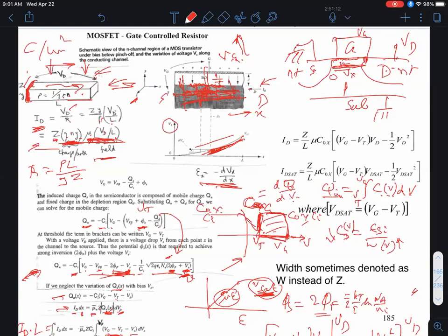If I look at the resistor from the top, why is that? Well, n has units of number of carriers per unit volume, times the thickness of the resistor Y will have units of number per centimeter squared. So that's how many carriers I see per unit area, looking at it from the top. Times q gives you coulombs per centimeter squared. So you can think of this as sheet charge, okay?